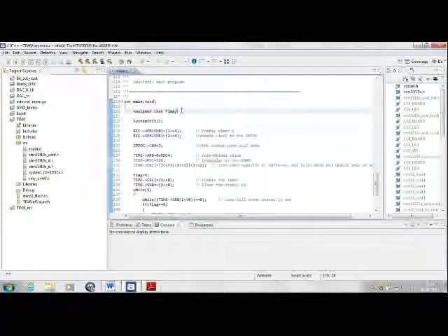After this, we use the normal system init function. In this function, we are making sure that the CPU is clocked at 24 megahertz. This is very essential in timer programming because we should know what clock is driving the entire peripheral bus, so that the timer is clocked with a particular value, and then the prescaler that we enter will divide this clock, and we will be in a position to judge what is the delay or time duration that we have programmed into the timer.